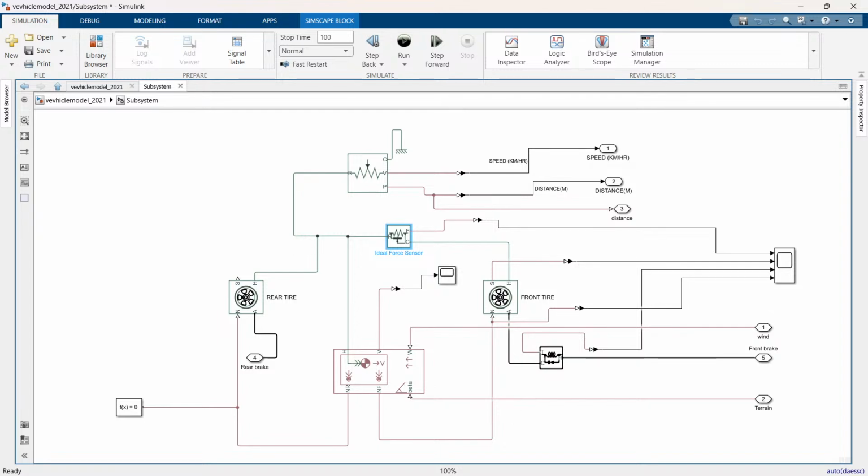So by measuring the forces at the hub, we can get a clear picture of the forces acting on the vehicle, including those from braking conditions and also the road conditions. This accurate measurement is very crucial for analyzing the vehicle dynamics, the vehicle's performance and controlling systems, like braking or traction. It helps us to understand our simulation model and ensure it matches real world behavior.